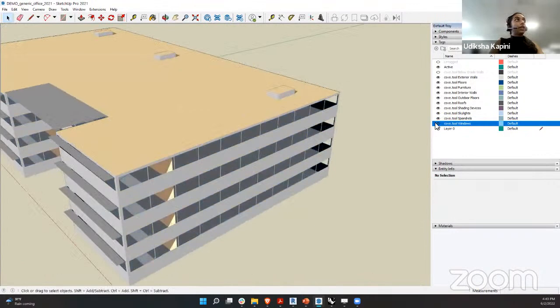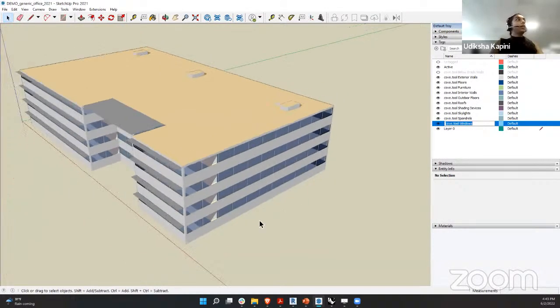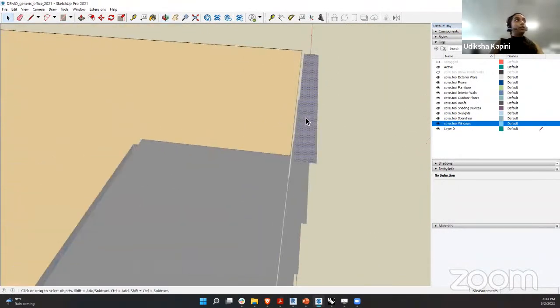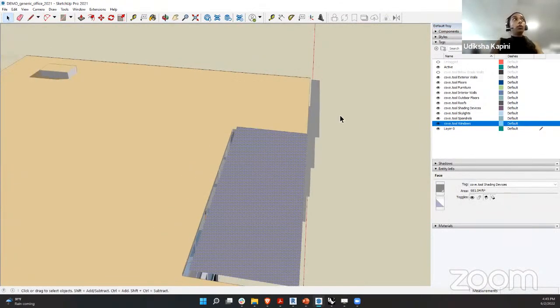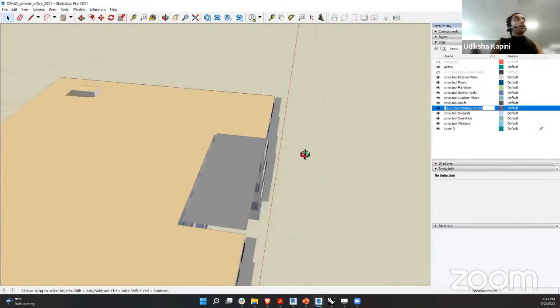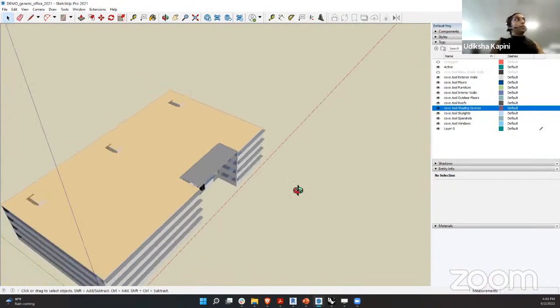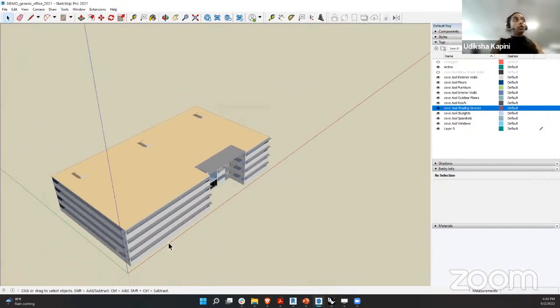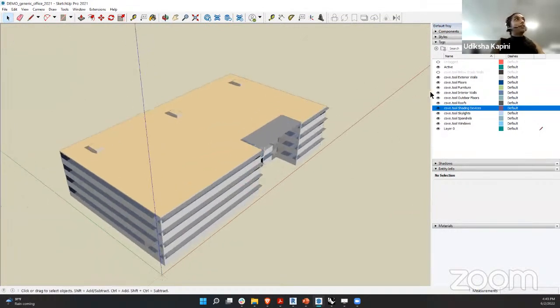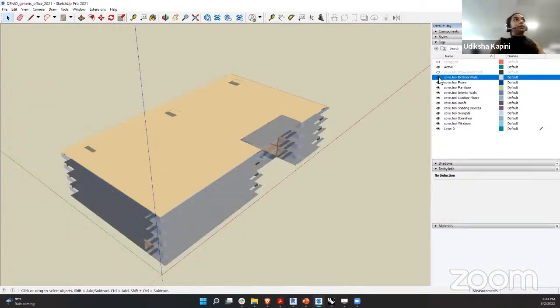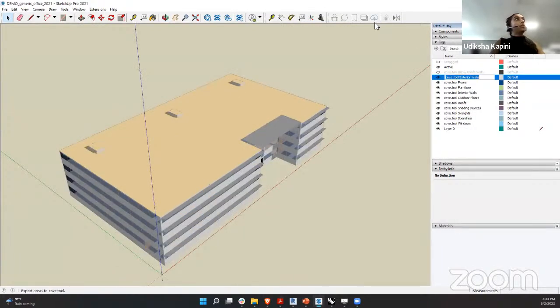And we are also, of course, able to identify glazing based on translucent material that has been applied to the object. And of course, any other parameter, for example, any horizontal objects that are outside the envelope will be assigned to the Cove tool shading device view. So these are certain rules that we've applied to the plugin to help classify your geometry and, of course, limit that cleanup process. And once you have correctly placed all your objects in the right views, we can then click on this export button to send geometry onto the platform.